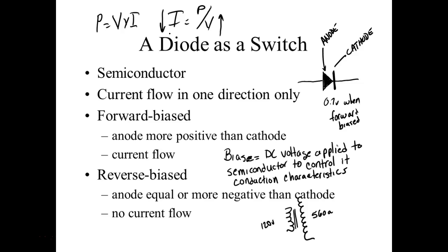They send it at an extremely high what? Voltage. Requires little current. I is equal to what? V is equal to I times R. So now my current gets down low. So if I transmitted power at 750,000 volts, I could send 750,000 watts of power with 1 amp of current.